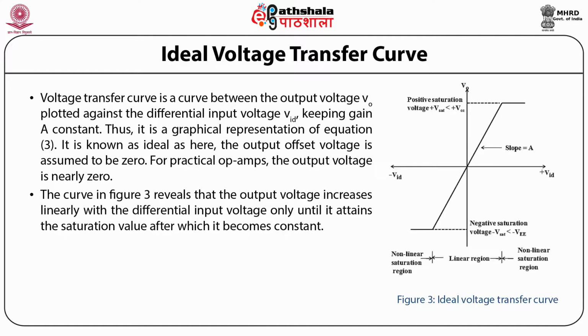The curve shown in figure reveals that the output voltage increases linearly with the differential input voltage only until it attains the saturation value, after which it becomes constant. The region in which the output voltage increases linearly with differential input voltage is called the linear region.